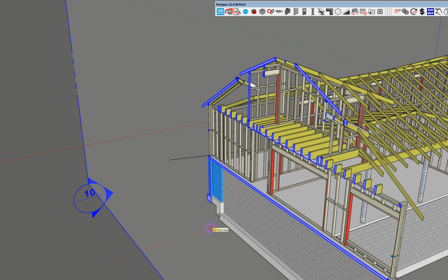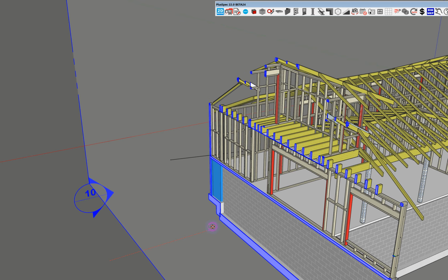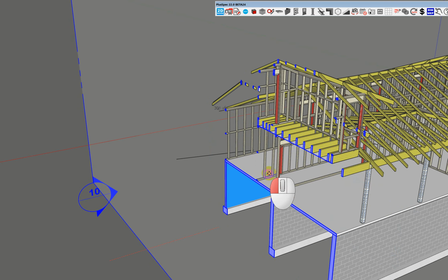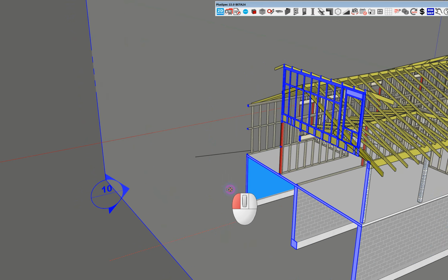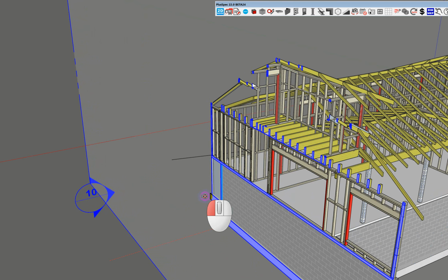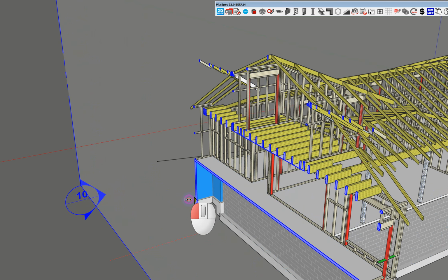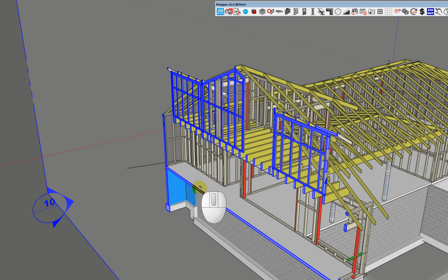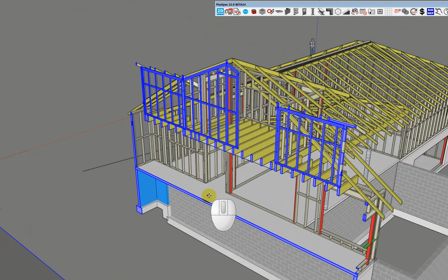Now, on the ground floor, we ran that beam all the way through because these joists are cantilevering over the top up here. So as you can see, those floor joists there are cantilevering from that wall there, and that's holding up the upstairs section and the wall there. So there's a lot going on here, guys. I just wanted to make sure that you're aware of it.